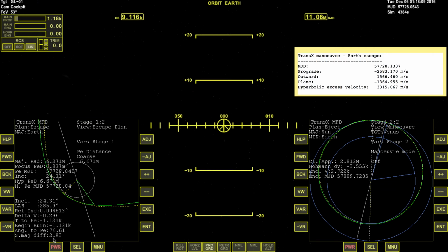This semi-major difference is an angular difference, so it says we're nearly 4 degrees out of true with respect to that line. So we are currently on an orbit that is 4 degrees out of true. So if we had shown a similar green line coming down to our periapsis on our green orbit here, there would be an angular difference between the yellow dotted line and the green line for our current orbit of 4 degrees. And you can see the manifestation, what impact that has.